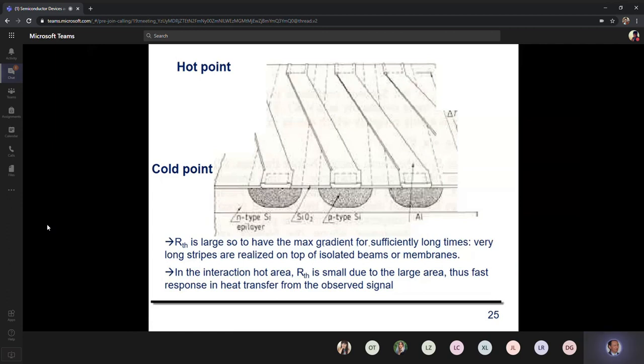This is a schematic of a real structure. So if you look at the circuit, we start with the substrate of silicon. Then we grow, you see the indication N-type silicon epilayer. We grow a thin layer of silicon of the N-type that is lightly doped.